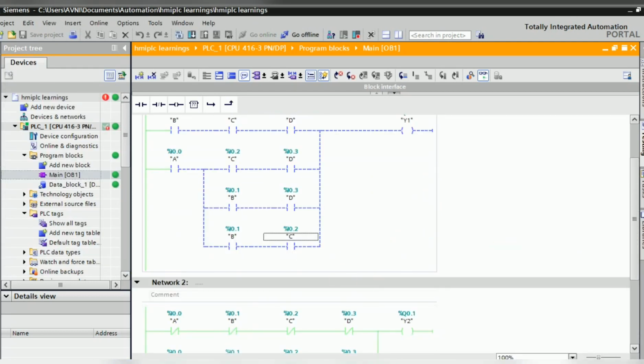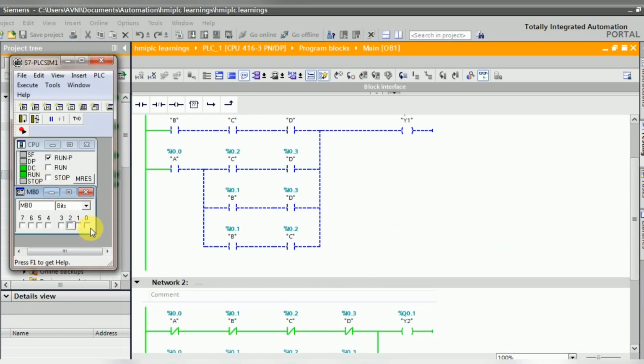Hence in total, only these 4 combinations, ABC, ABD, BCD and ACD, have 3 or more than 3 inputs in the high state. Hence this can be accomplished by connecting these combinations in series, with parallel connections to each other, as shown in the ladder diagram above. Output Y2 is high in only 2 conditions: whenever all the inputs are set to 1 or are reset to 0.